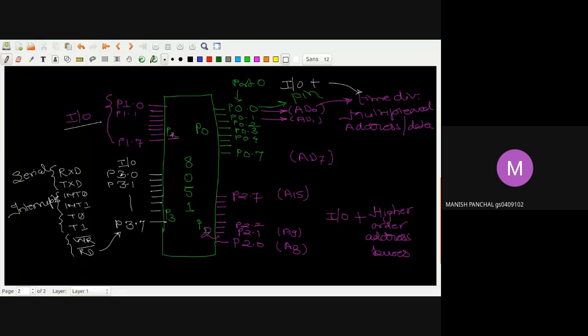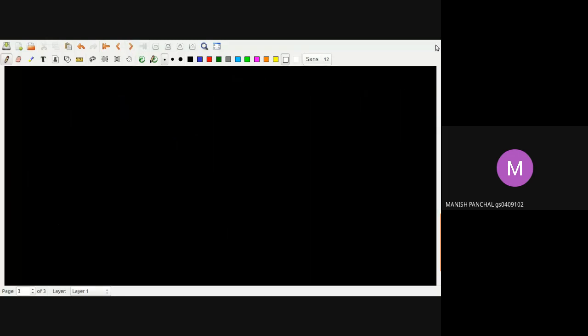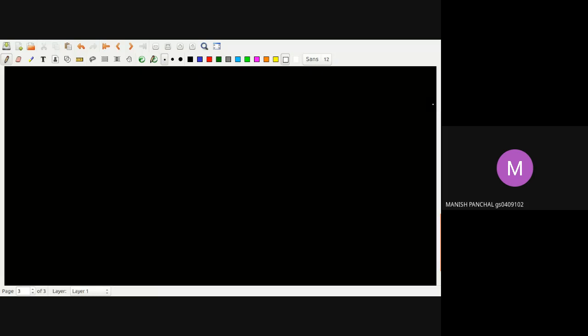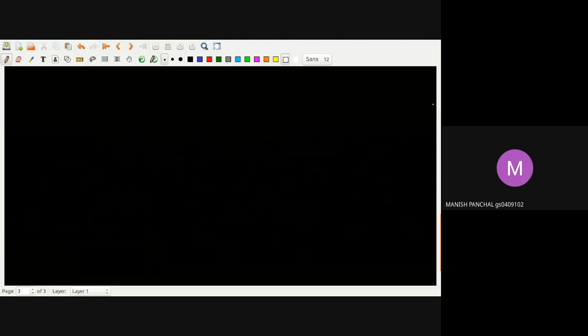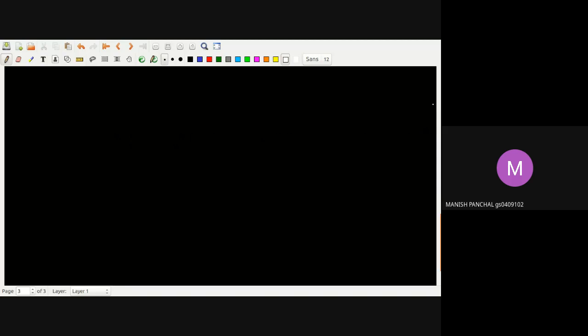Okay. So now, as you know, we have already talked in the case of the 8155 and 8255 that whatever the ports you are talking about, this port should have the facility for the buffer and the latch. Why is it so? Because whenever any input device wants to communicate with any microcontroller, this device should put the data on the tri-state buffer, and then after getting the proper control signal, the tri-state buffer will release the data to the data bus of the microprocessor or the microcontroller.